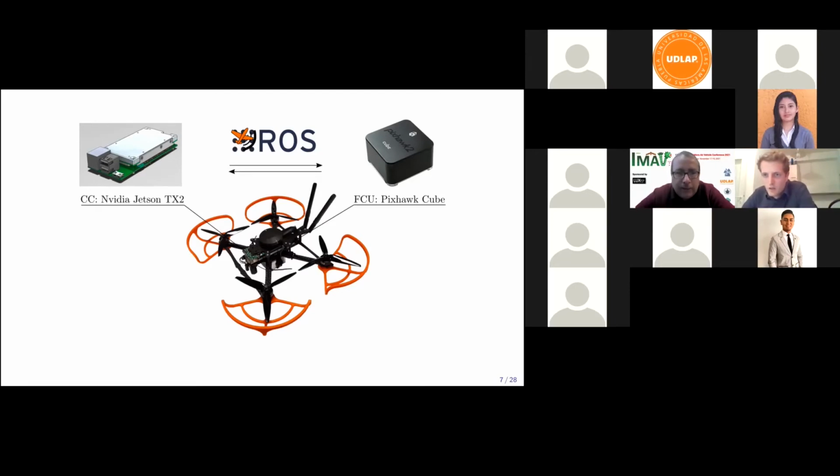So the human pilot is controlling a second order system, do you think? Because if he sends angles, he's commanding a second order system. Yes. The human pilot, if he is flying in stabilized mode, would be sending references to a system that always acts with a little bit of a delay and the transition. And this transition, as I show here, can be modeled approximately as a second order system.